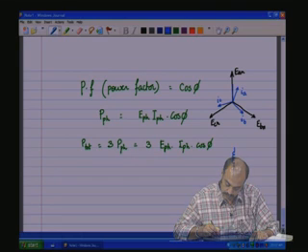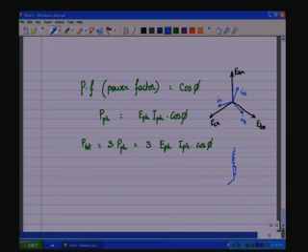How this comes about? You will see that if you have a circuit something like that, as shown here, this is A, B and C, this is inductive in nature, RL circuit, R, L, R, L, R and L, same R's and L's, balanced load. So, you will see the currents lagging the voltage in every phase.